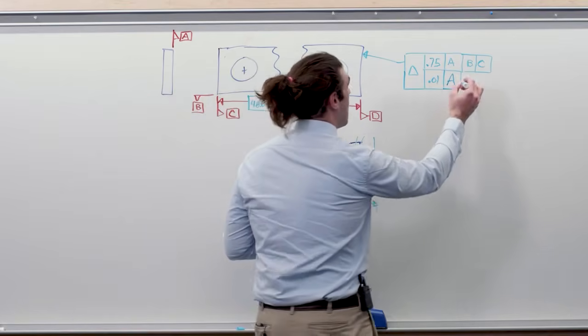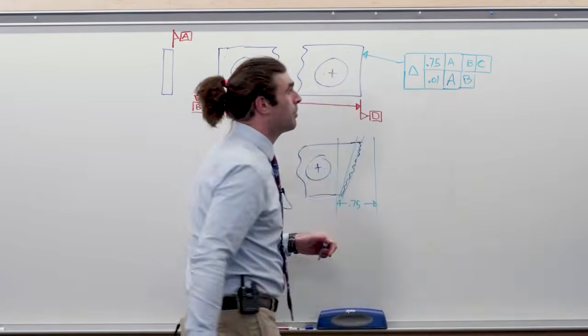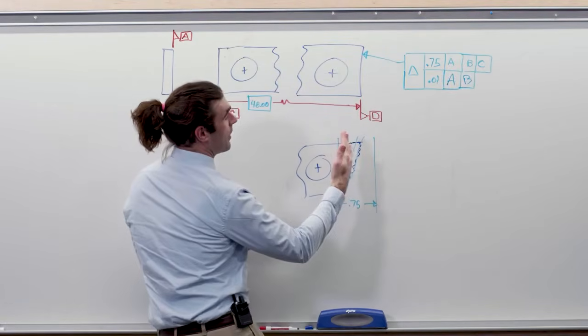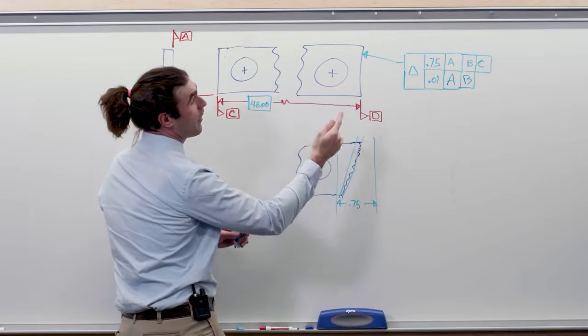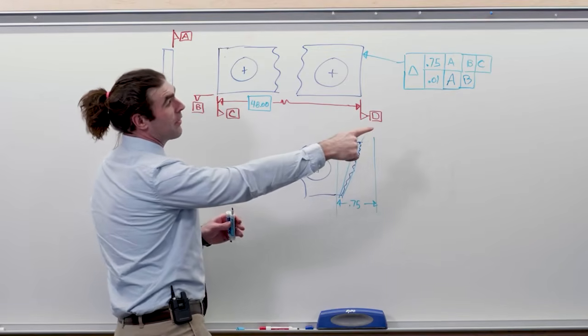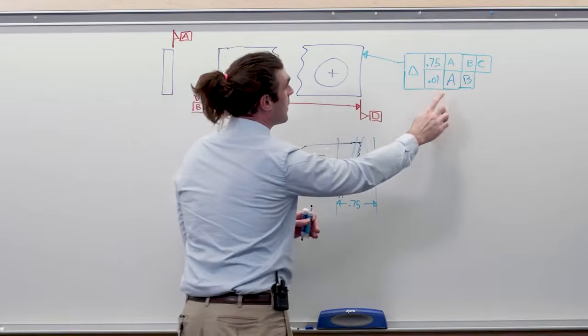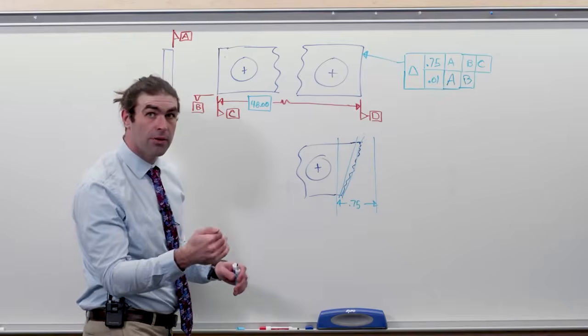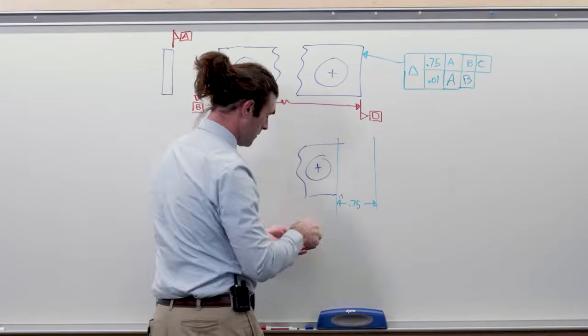So I'm going to skip ahead to datum B here. What that's going to do is snap this into shape. So now we got to be flat to 10 thousandths. We've got to be perpendicular to datum A, which is the largest surface, and perpendicular to datum B.